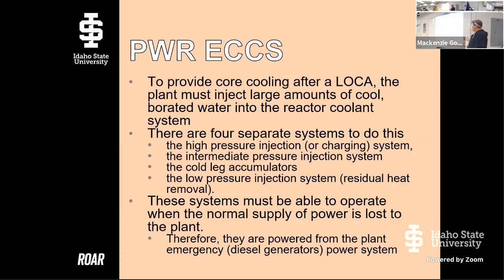So it sounds like residual heat removal is not significant, but after a reactor stops creating fission, just like your campfire, after it stops creating flames, still has residual heat in the coals. The nuclear fuel is the exact same way. You still have heat, okay? And so this has to be able to continue to provide cool water to remove that residual heat.